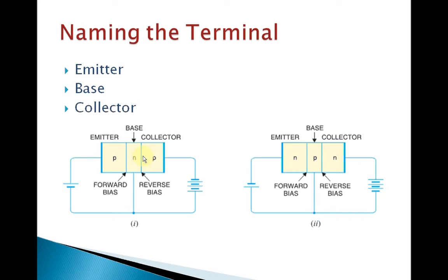So in a nutshell, we can say that a transistor consists of 3 extrinsic semiconductors. 2 of them will be the same and another one will be opposite. That means the same type of material is sandwiched with the opposite type of material, which forms a transistor. It has 3 terminals: emitter, base and collector. It has 2 junctions: the emitter-base junction, and another one is the collector-base junction.